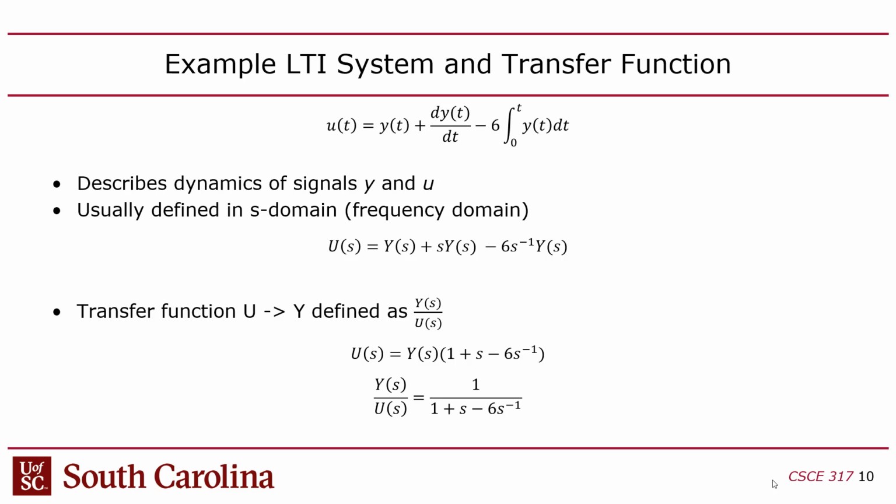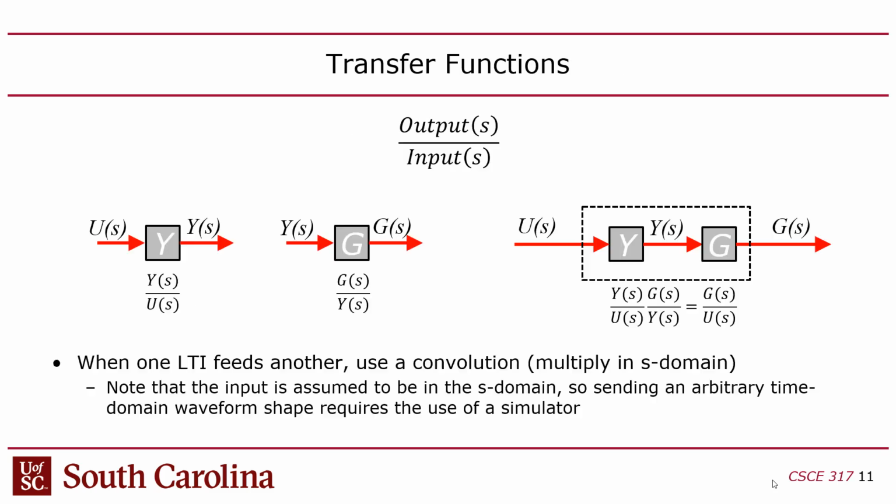It's a ratio of polynomials. Well, there are values of S that will make the denominator 0, where you'll divide by 0. And for every possible value of S where the denominator is 0, that's a pole, right? Likewise, there are zeros, where every value of S gives you a 0 in the numerator. But in the case of checking for stability, you're looking for poles.